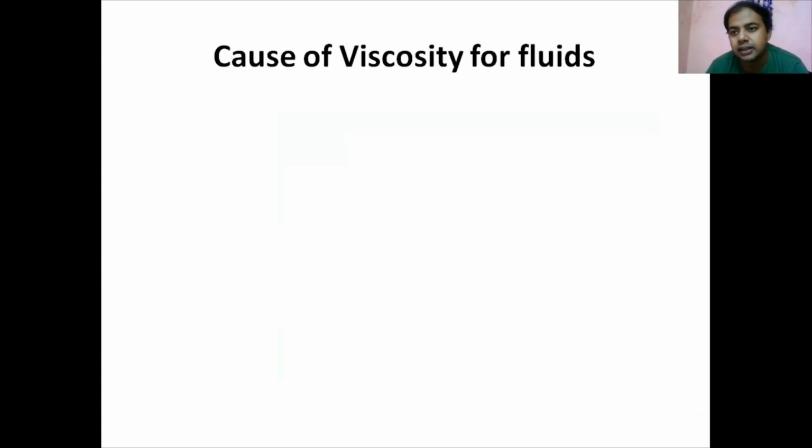In the case of the liquid, the most dominant feature is the intermolecular attraction force, because liquid molecules are strongly bound compared to the gas. That is why the attraction force is more. If you raise the temperature, the attraction force will decrease and viscosity will also decrease.